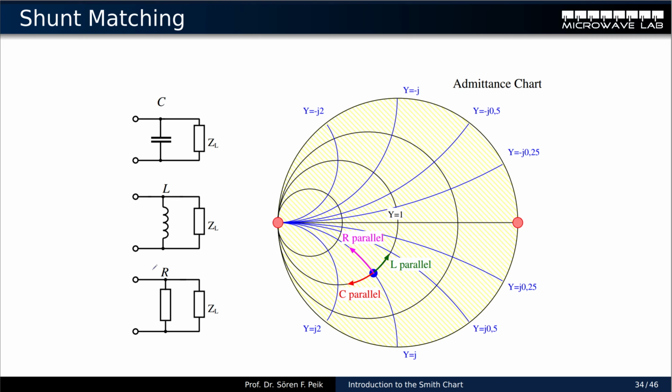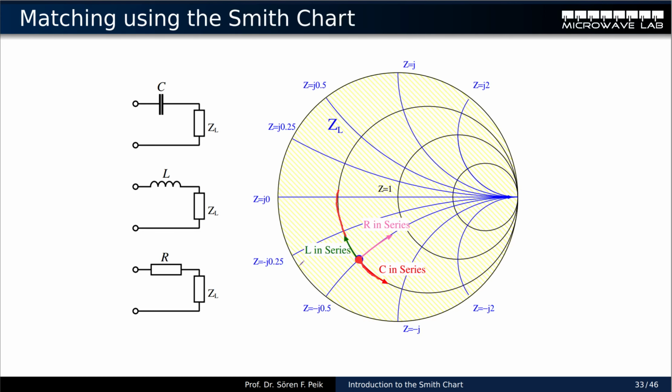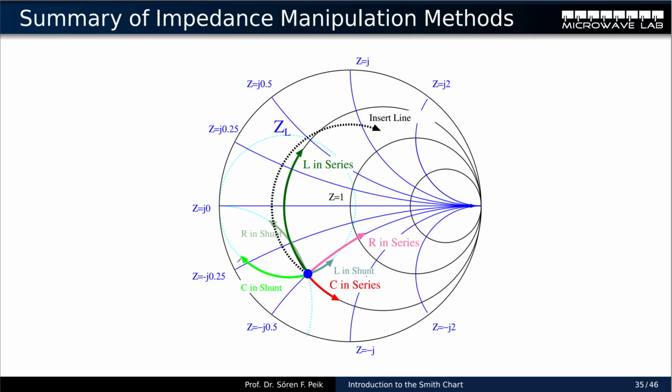When the admittance of your R becomes extremely big, basically you have a very small resistance, then you go towards the short. When coming back here, when you put in a resistance and the resistance becomes bigger in series, you go towards an open, which is this point down here. Okay, more examples about this coming up, so I think you get the idea after a while.